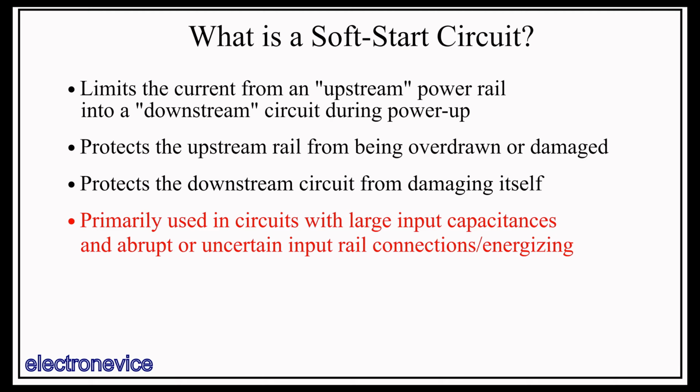Today we will be discussing 3 different soft start circuit design architectures, but first we'll talk a little bit about input capacitance for a DC system to give you an idea why such a circuit might need a soft start. I tend to usually talk about DC systems because they are the kind of systems I generally work on. However, inrush is present in AC systems as well, though the mechanisms for it are somewhat different. Though for AC systems that have a rectifier that feeds into a large input capacitance, inrush is remarkably similar to that of a DC system. So soft starts are often required for AC systems as well.